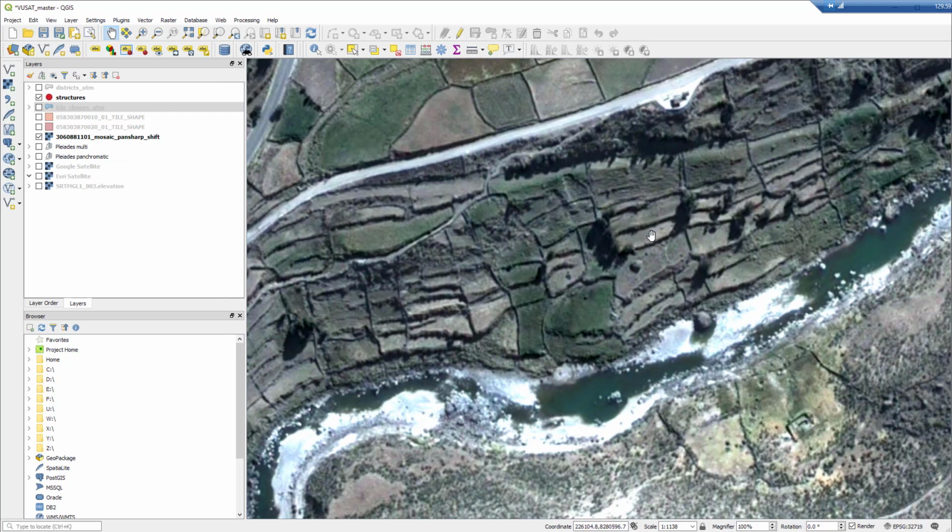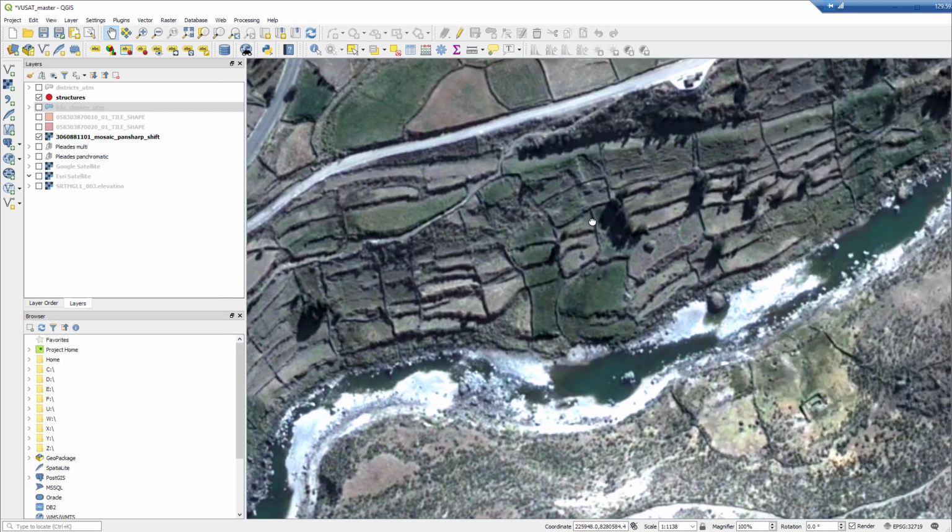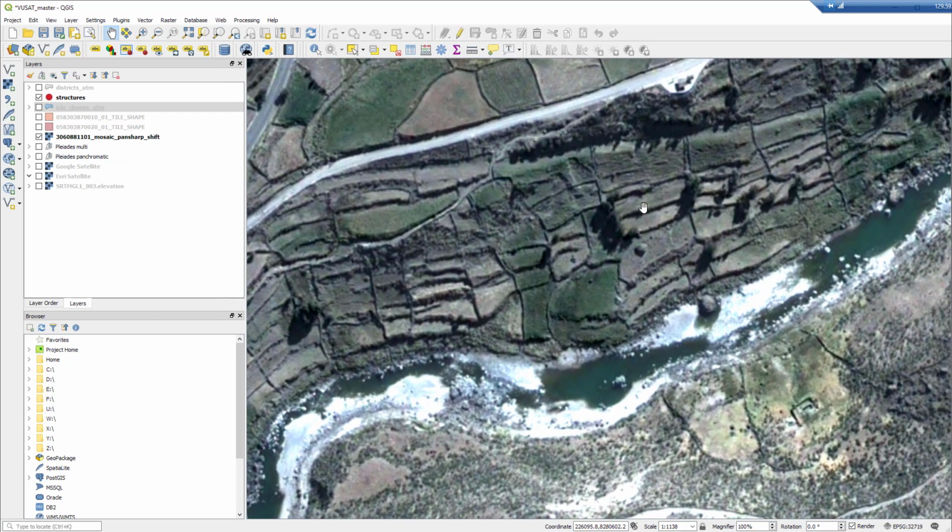So the tops of these terraces slightly slope towards the downslope, and the irrigation water comes down, and they can guide the water over each terrace, and it cascades down to the next one, and so forth as you go down. Okay, so those are bench terraces, these kind of narrow ones.